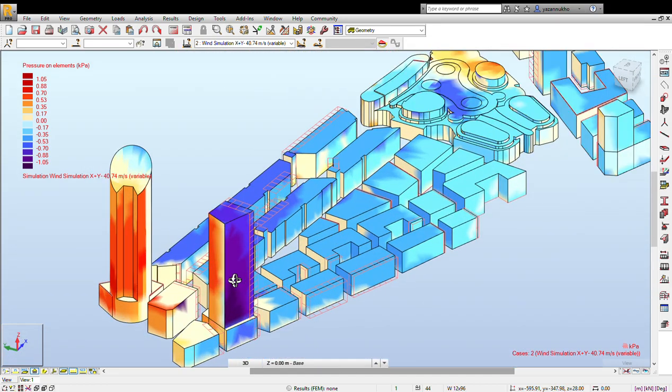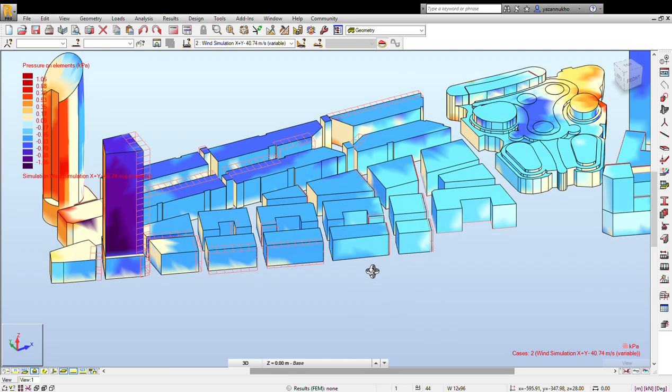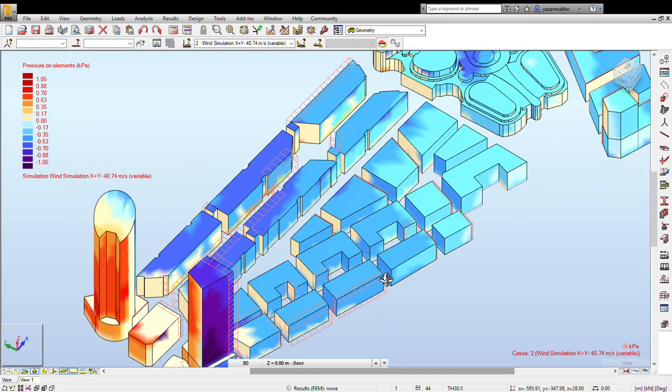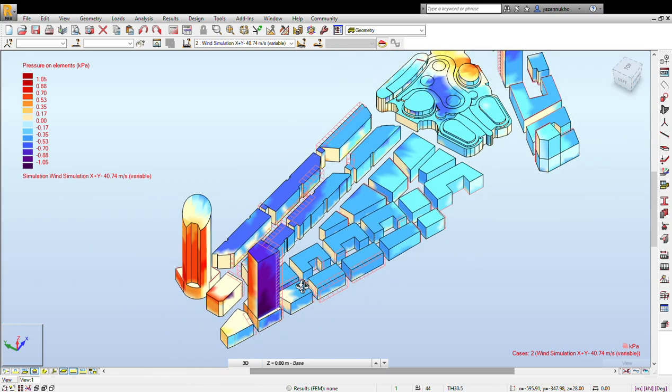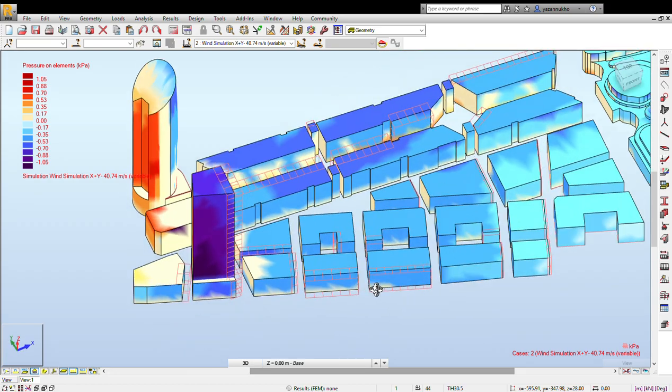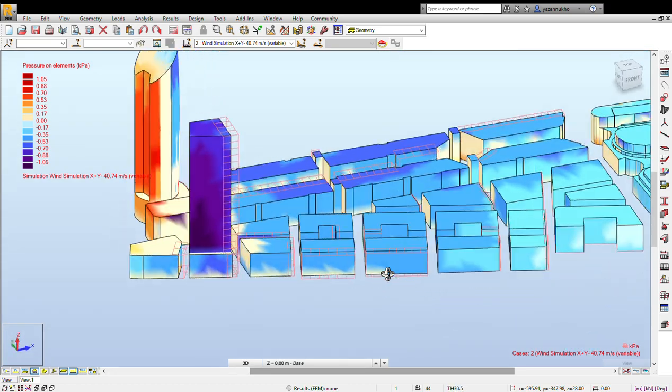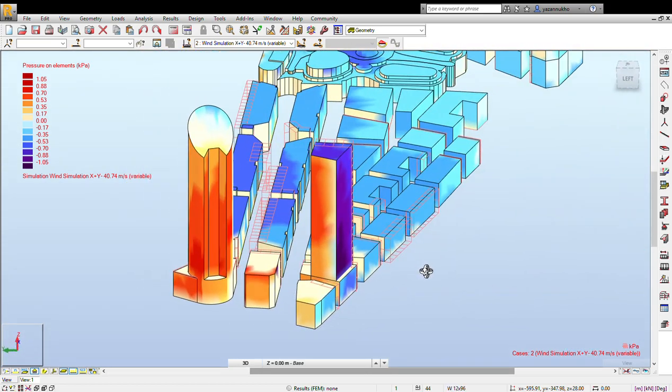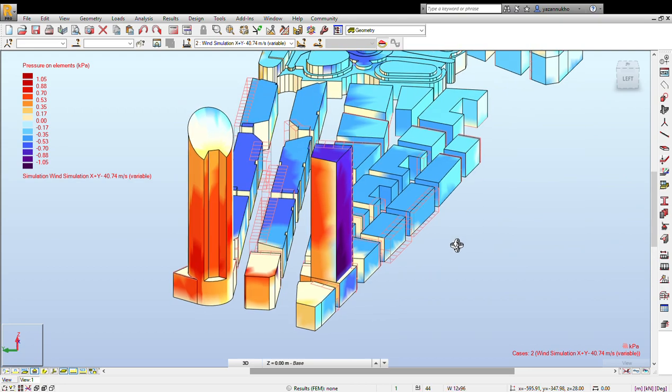Within the same software, we can detail a specific building to have parts where we have aluminium curtain wall, other parts where we have cladding, and carefully study each of these elements separately and generate a full spectrum of wind loads that need to be accounted for during the engineering of any facade for these buildings.